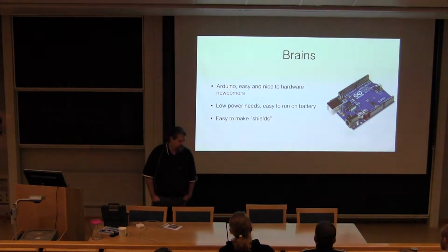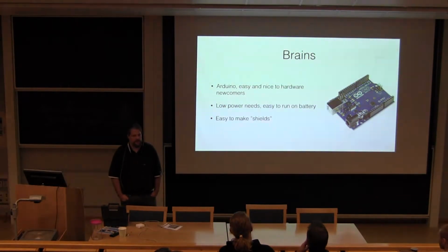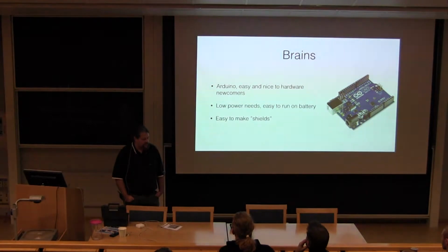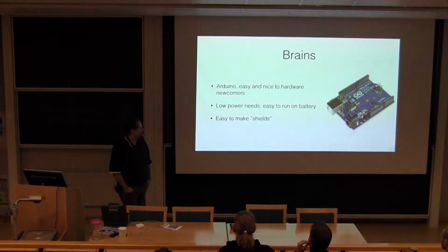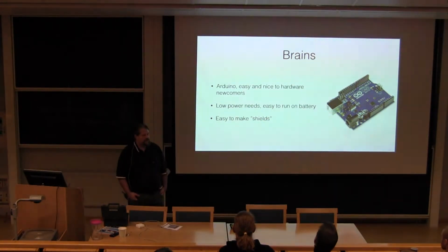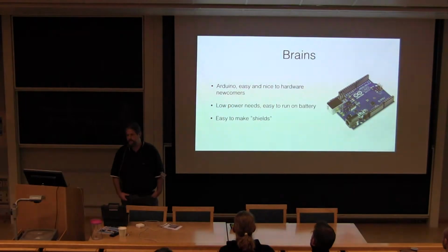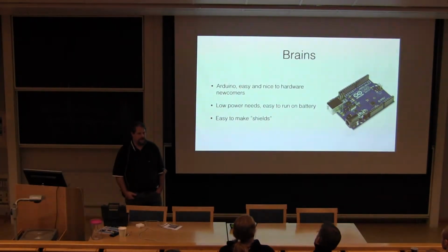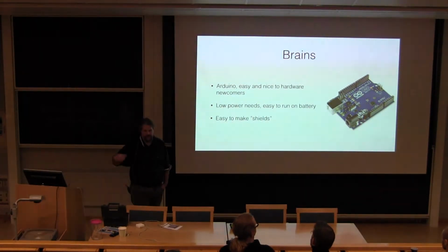The Arduino is also very low powered. I heard numbers that they can run an Arduino for a year from a 9 volt battery. They had to change something in the software, mainly the sleep function, because the standard sleep function actually runs the CPU for that time.